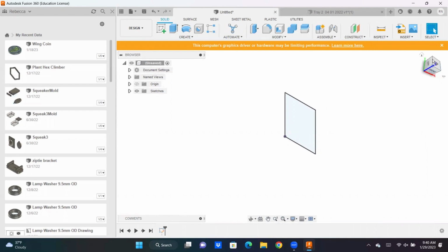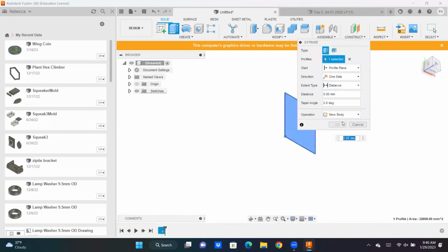So here is the extrusion process. You're going to extrude, you're going to select the surface that you want to extrude. The automatic selection will be to make it a solid. That's that first type line. You're going to select your part, the distance that you want to extrude. There are some details that you can change if you want, but this is the most simple.